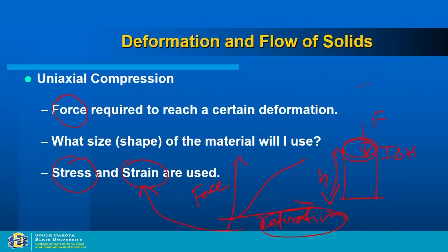When I say applying force, you are going to compress a sample at a particular speed, right? The test speed is also an important variable. If that lab is going to do the test and my lab is going to do the same test for different samples, we should make sure that we both use the same test speed.